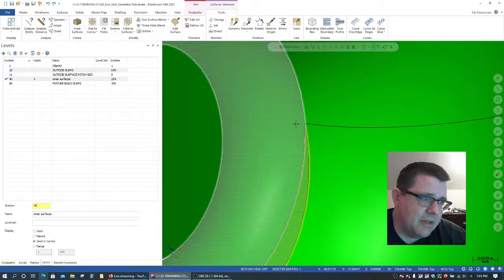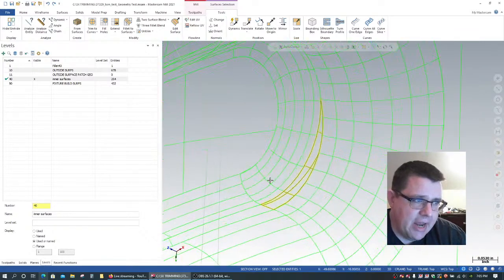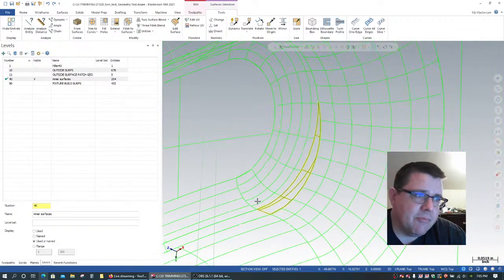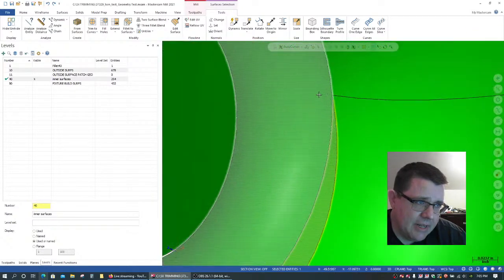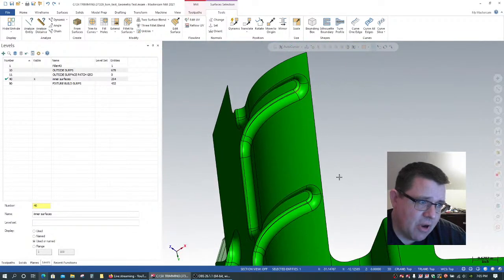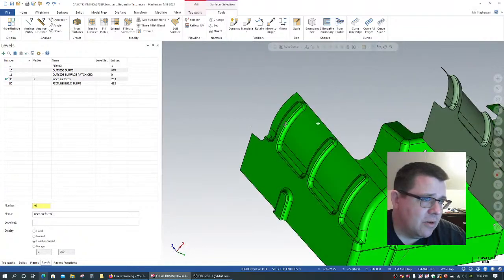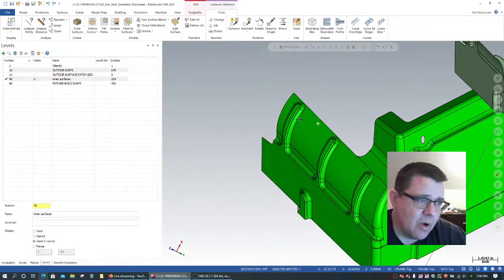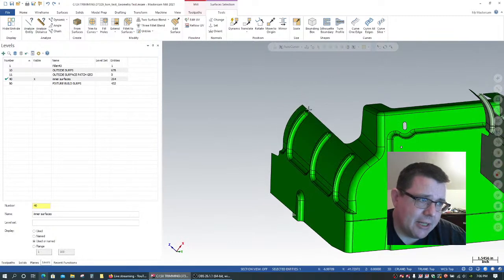And if I grab this guy and I unshade, based on the shape of the UV curves right here, I can already tell these little guys in here are going to give us problems when we try to generate this into one big happy solid.